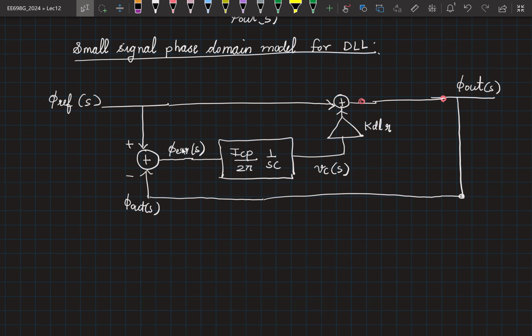To any small signal variations, will the loop settle in time very, very greater than TRF? Correct. To any small signal variation, the loop is going to respond very slowly compared to TRF. Because even if there is a variation occurring, every TRF is when it is going to detect it, and every TRF it is going to correct for it by a small step. But that is an issue, right?